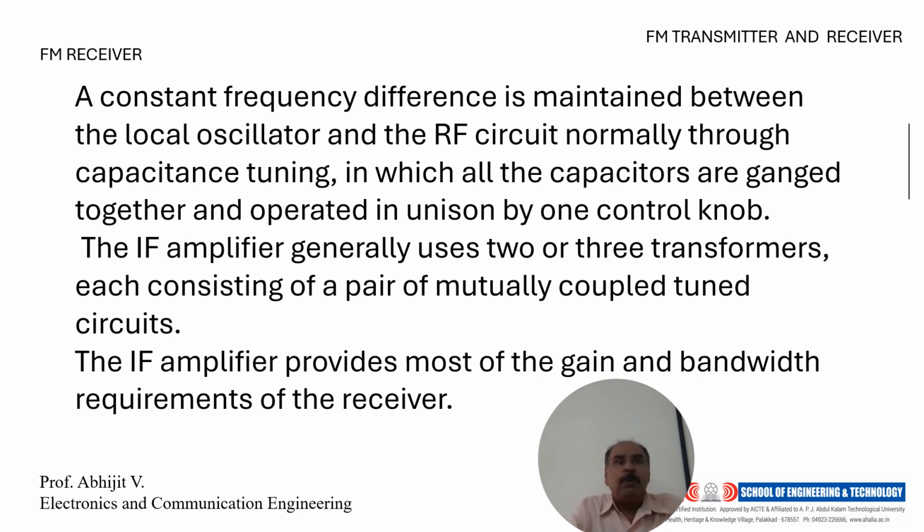We have a group of capacitors that is being used for tuning and setting up a radio frequency and intermediate frequency, to receive only the signals that we require. So this frequency which stands in between the frequency band is known as the intermediate frequency, and this particular frequency, which is in the center of this band, is picked up and amplified.